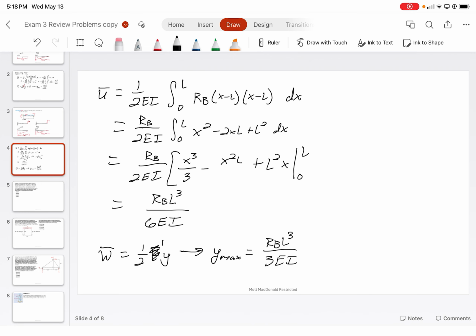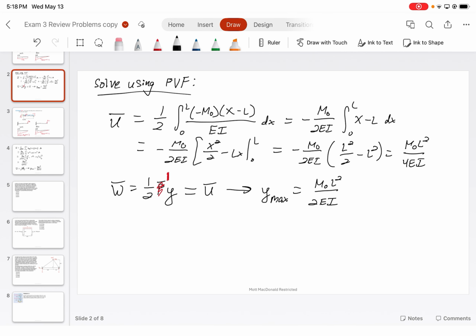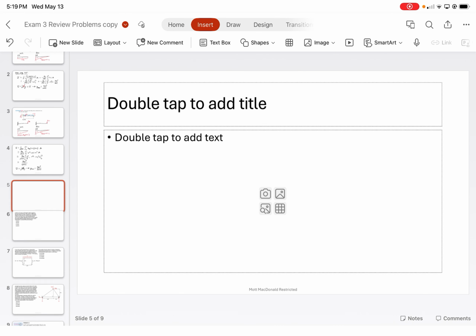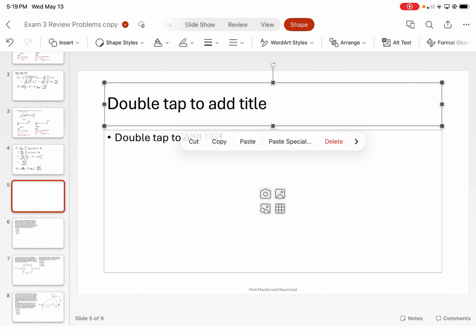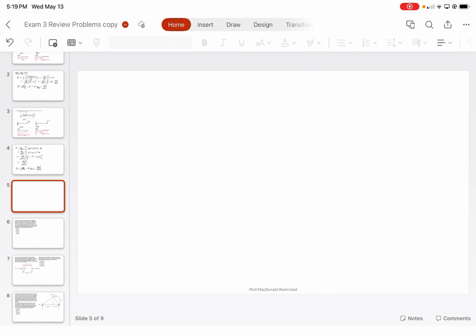And then for a moment, the deflection is ML squared over 2EI, which is what we had previously computed here. So the values are correct, which means our assumptions for calculating the deflections currently are correct. All right, but that doesn't exactly solve the problem yet. Now we only found the deflection, so now let's apply compatibility.